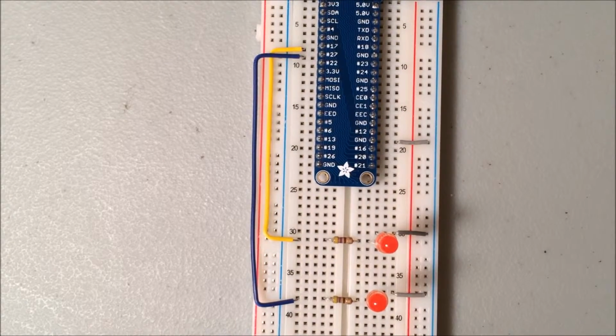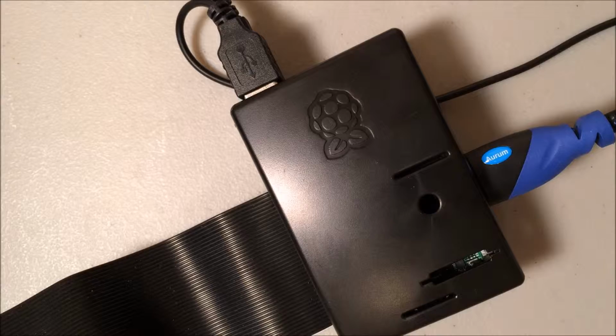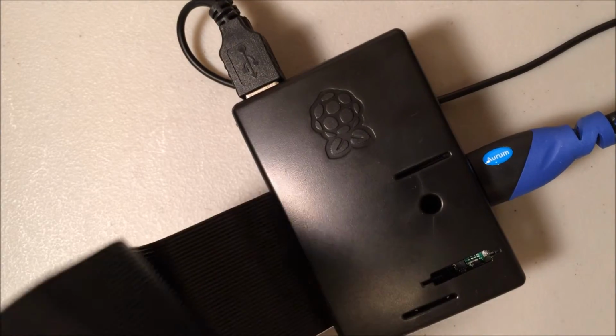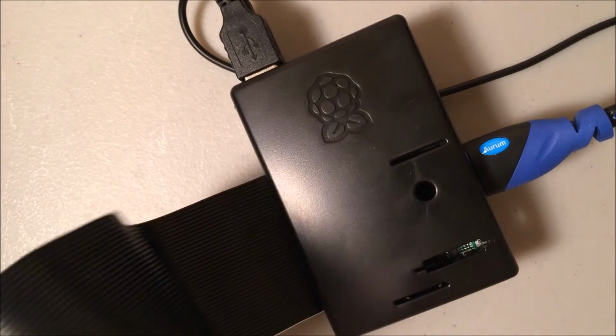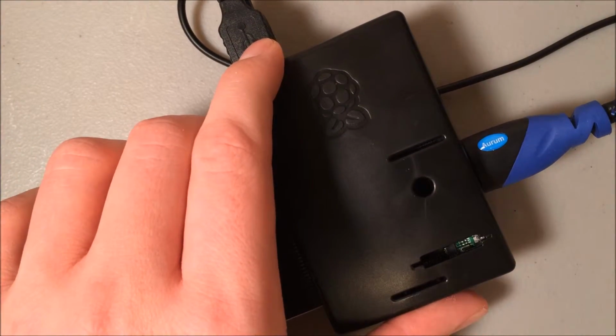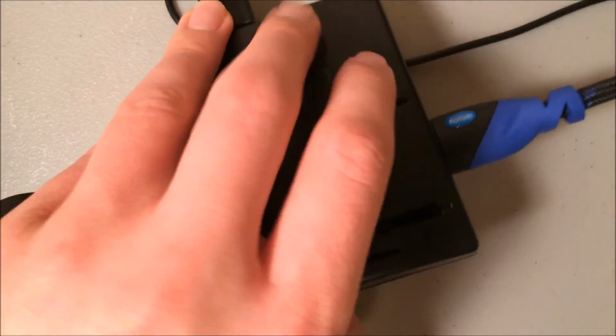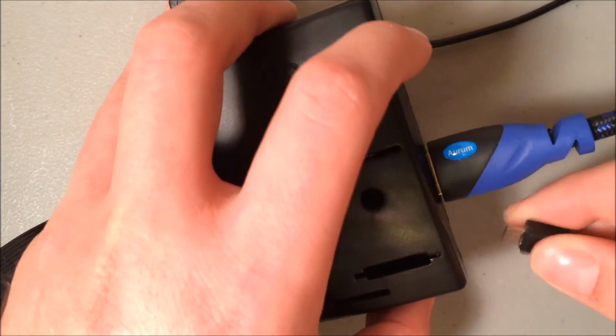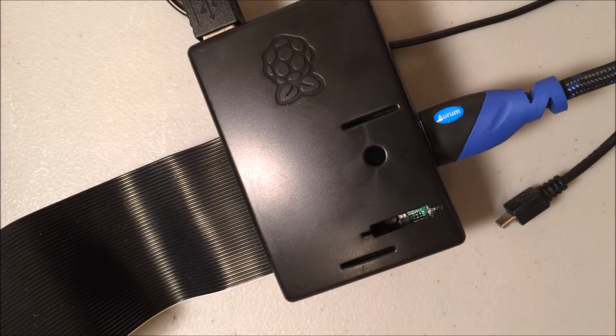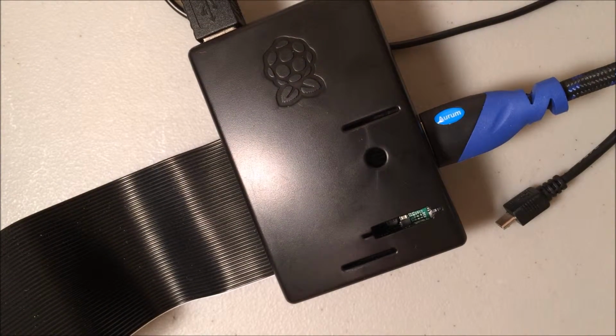So let's go ahead and boot up our Pi and get started with programming. Make sure that you have the T-cobbler plugged into the GPIO ribbon cable, you have your USB mouse and keyboard connected, your video cable connected, and your micro SD card inserted with your operating system installed. Add your power cord and it'll boot up. Remember that your username is pi and your password is raspberry. Use startx to launch the desktop. Also remember to shut down your Pi before making changes to your circuit. You can use the shutdown icon on the desktop or use sudo halt from LXTerminal.